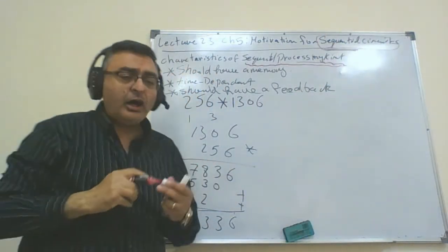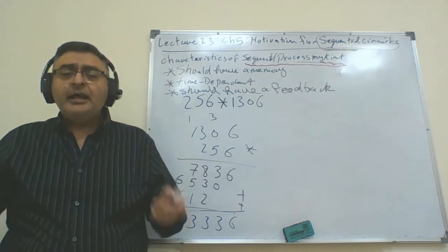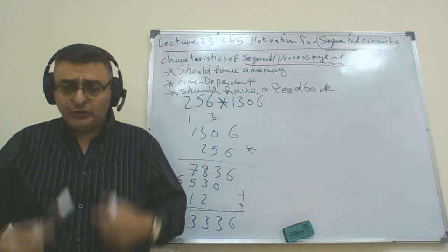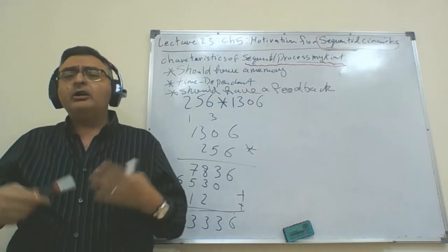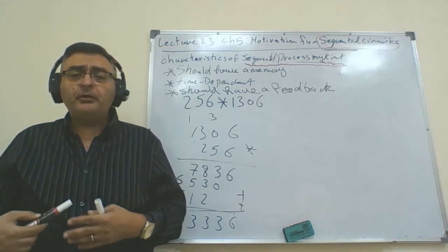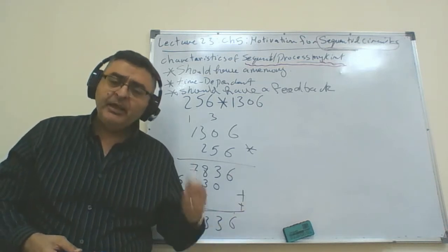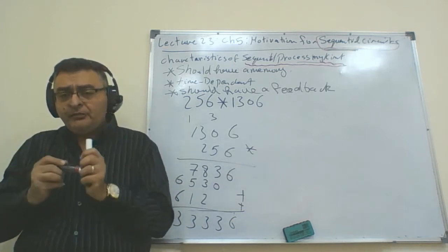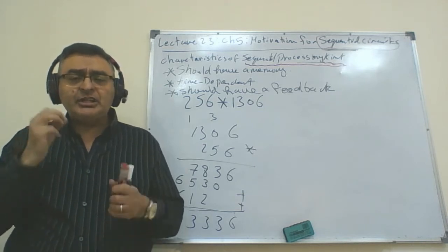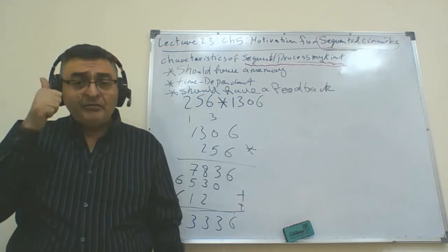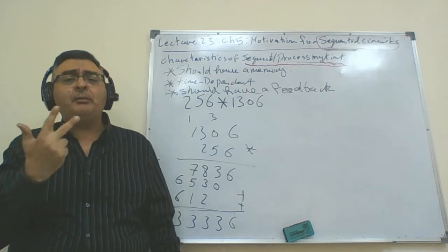Sequential circuits are digital logic design circuits, but they have to satisfy 3 conditions that actually allow those kind of circuits to perform complex operations, hard operations, or operations performed on long numbers that we were not able to achieve easily in the combinational circuits. This is the main difference between sequential circuits and the combinational circuits. 3 characteristics are added here. The system should have a memory. The system has a feedback. The system is time dependent.